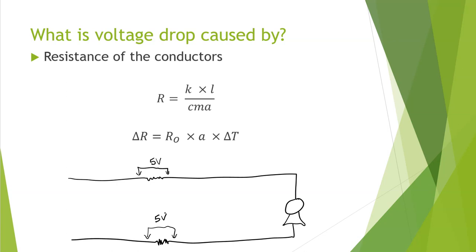And it's that we're concerned about, because ultimately if we are losing 10 volts on this given circuit, let's assume that the circuit derives from a 120 volt source. If we are in fact losing 10 volts on this circuit, just on the conductors, then that will only leave 110 volts for the load. And at 110 volts on a 120 volt circuit, that represents only 92% of what it should be, 120. And therefore we're looking at an 8% voltage drop in this scenario.